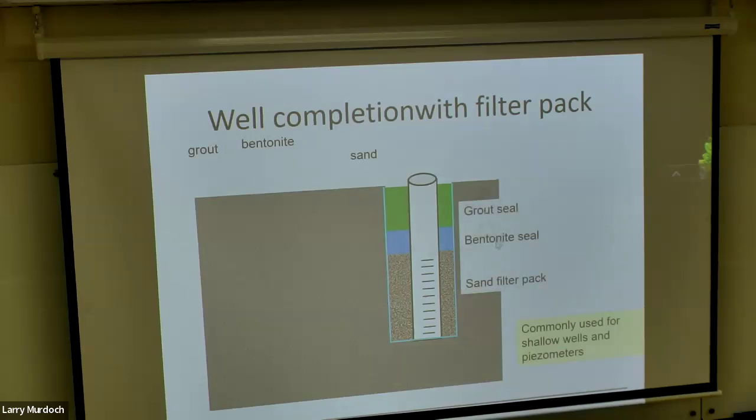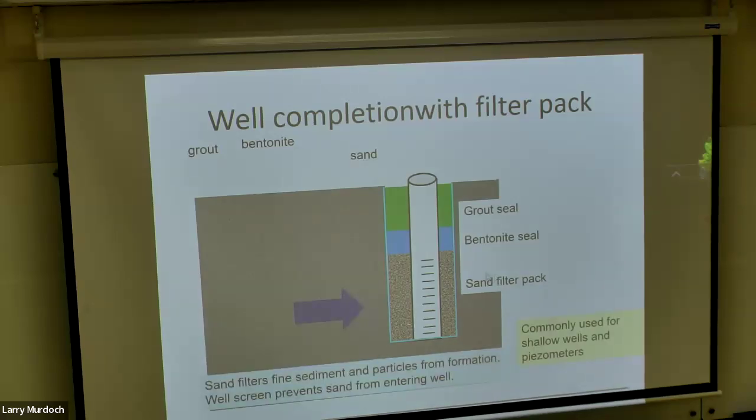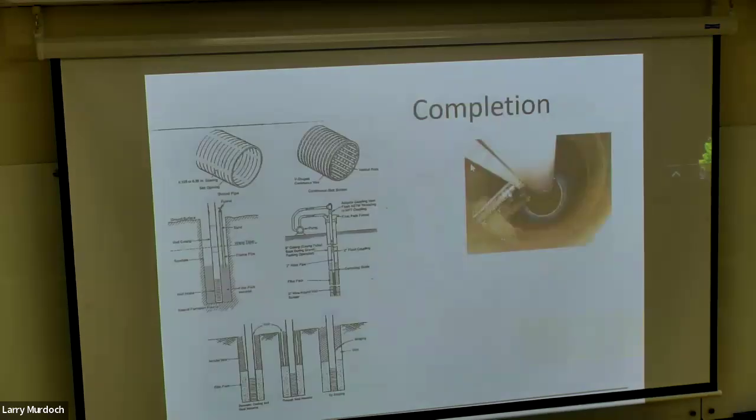So you have a grout seal, bentonite seal, the sand filter pack. So this is the action. Sand filters fine sediment particles from the formation, the well screen prevents it. So there you go. Stop that from happening.